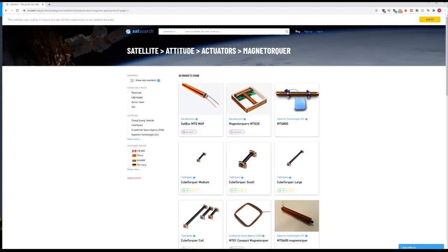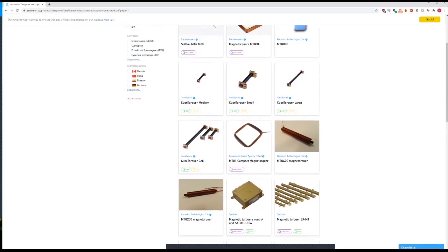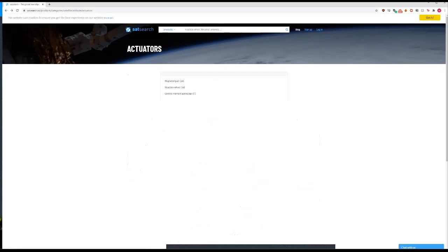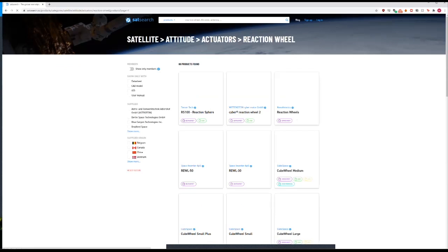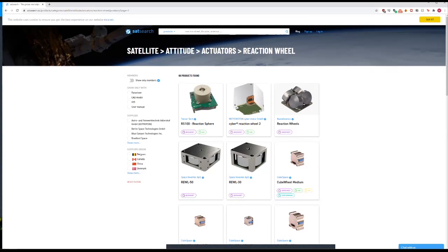So yeah, but magnetorquers are becoming pretty commonplace. They don't actually have to be independent systems. It's becoming increasingly popular to embed them inside the solar panel PCBs as a really thick copper pour in the shape of a spiral. Those are magnetorquers. The others are reaction wheels. Reaction wheels are the more traditional way to torque your spacecraft about.